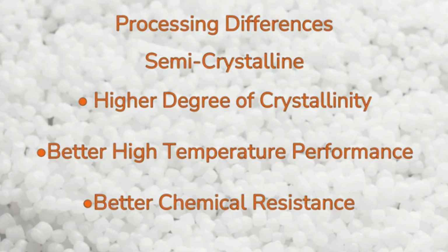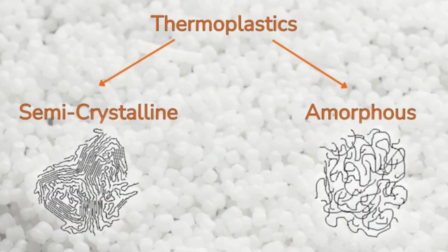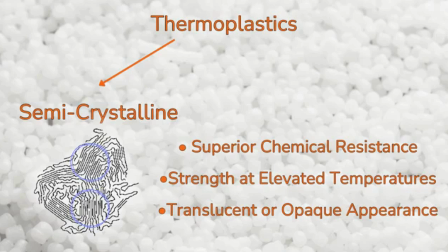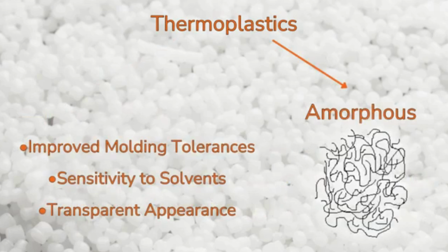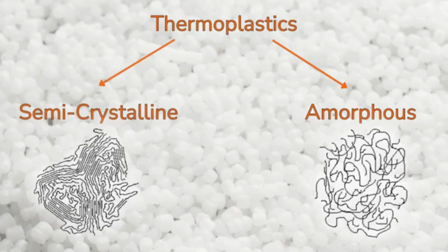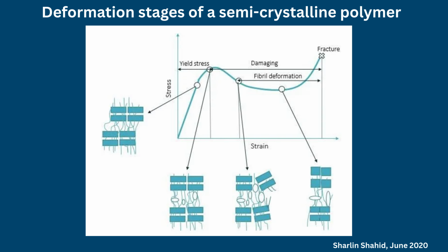This apparent contradiction arises because low Tg alone does not guarantee macroscopic ductility. For a semicrystalline polymer to undergo extensive plastic deformation, stress must be effectively transferred between neighboring crystallites. Tie molecules provide this connectivity. If their population or effectiveness is insufficient, deformation becomes localized near crystal/amorphous interfaces. Cavitation, interlamellar separation, crack initiation, and catastrophic fracture can then occur before stable plastic flow develops.